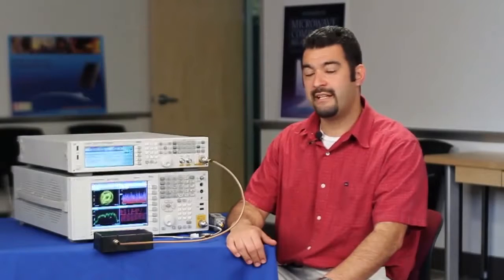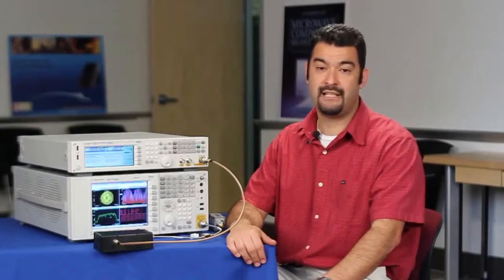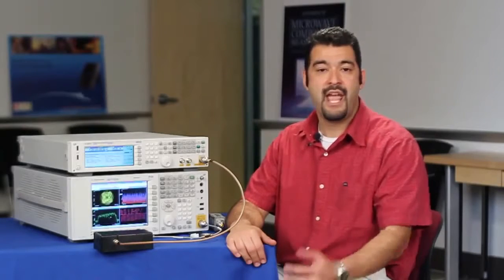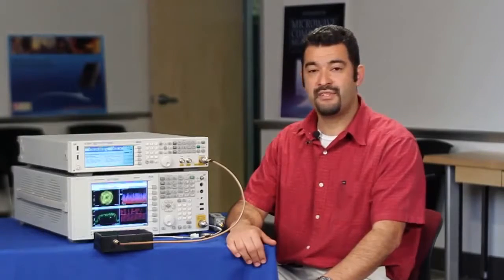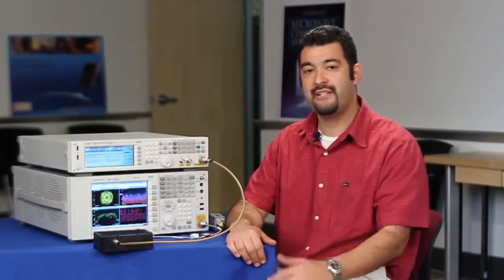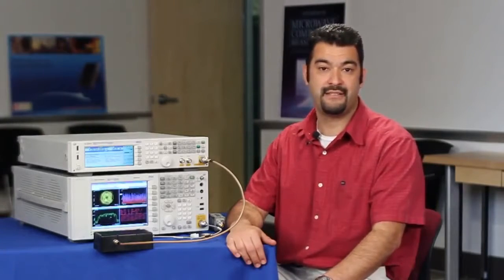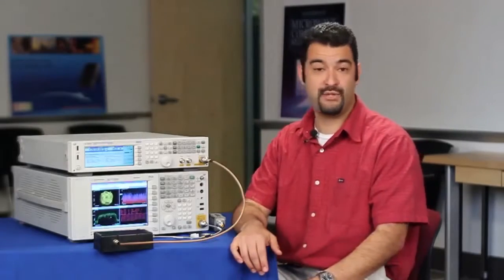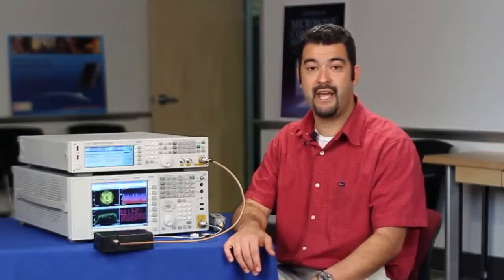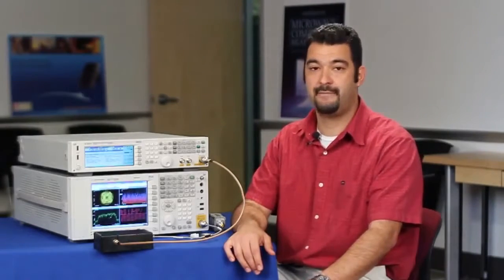RF engineers are designing next-generation transceivers to support wider bandwidth for technologies such as 802.11ac and LTE-Advanced. As you go to these wider bandwidths, amplitude flatness and phase error become more significant. Your challenge is to maintain the EVM quality and ACPR performance of your devices going forward. Maybe in your production line or in your verification test rack, you might have a switch matrix where you have cabling and other issues inside the test system which introduce linear amplitude and phase error.